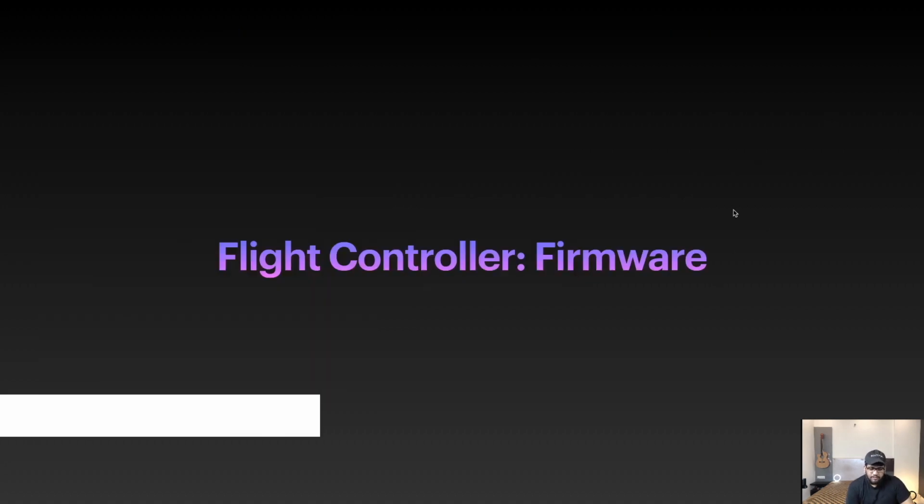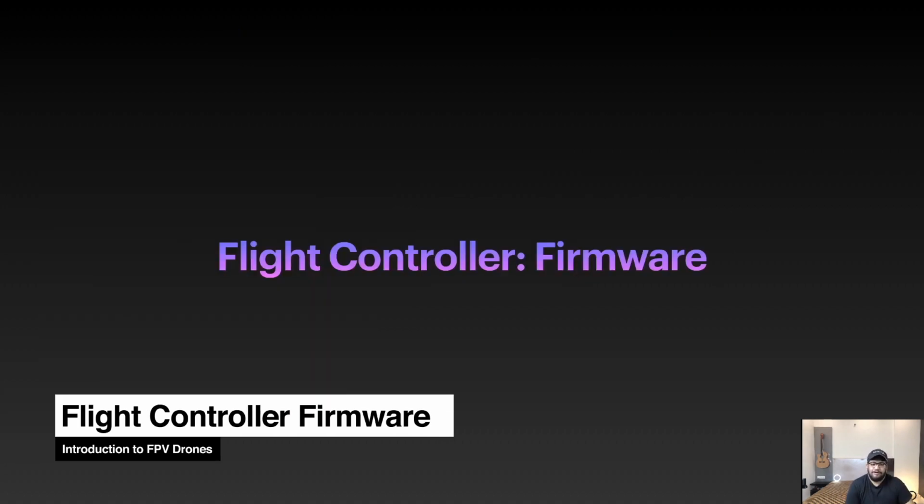All right, so let's talk about the flight controller firmware. This was a relatively very advanced class where we discussed the digital signal processor. We discussed implementing a complementary filter and what a notch filter is. We also discussed control systems and algorithms: proportional, integral, and derivative. The question is, if I want to design a flight controller, do I need to program everything into that? The answer is yes, you have to. If you want to have a stable flight, then you need all that.